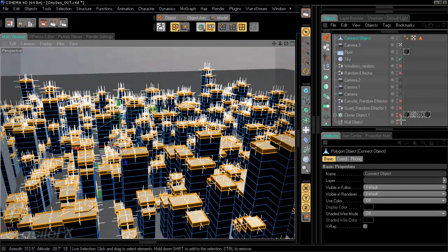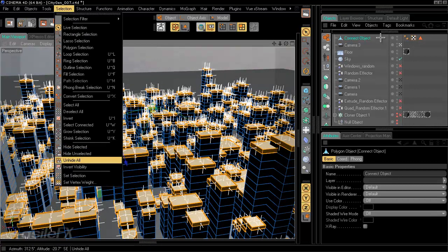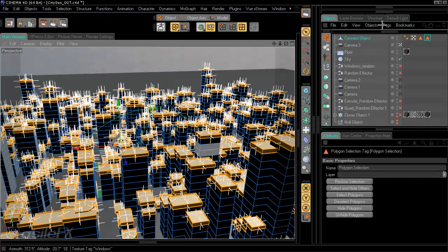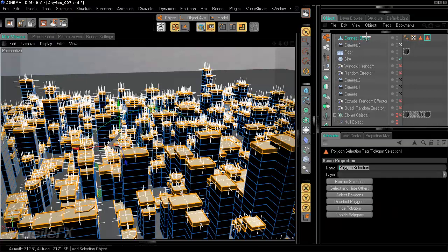So that way we'll make sure that there are no window textures showing on that portion of the building. Set the selection, and now we have something we can just call a topper. So top and then topper. So just the single polygon from the original selection that was used to extrude everything, and then the topper, which is now that set of selections from the top.